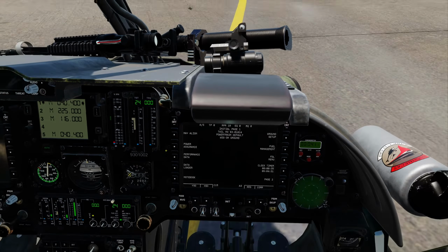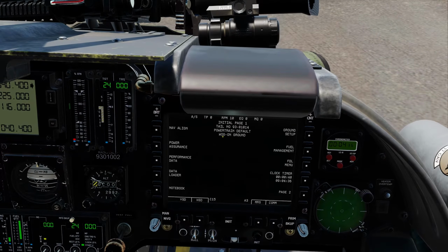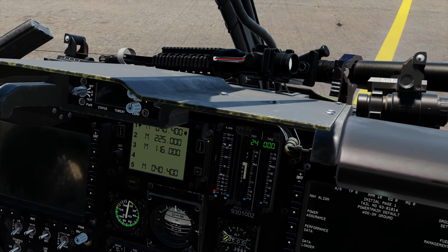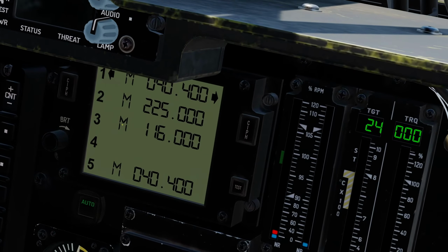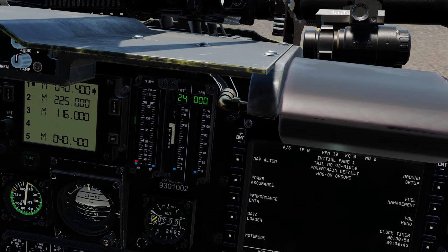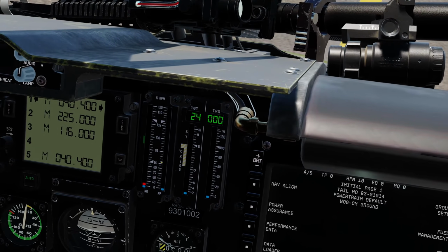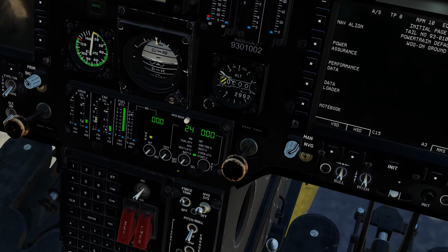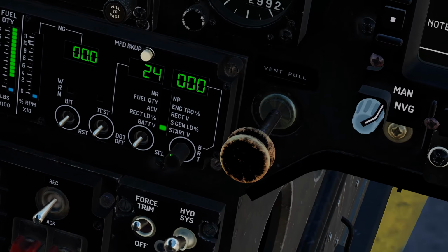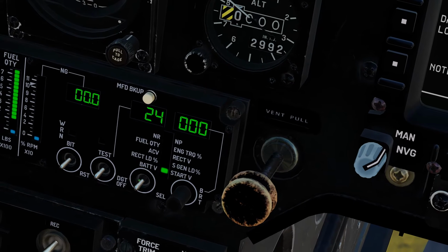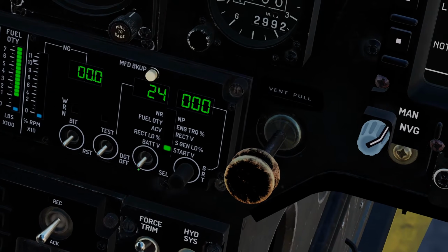And now you can see that the multifunctional display, or the MFD, has come on with the battery. Next, you can see that the RFD, the remote frequency display, which are the radios, has come on there on our left. Also, these have lit up and we've got some readings, and these are called the VSIs, or the vertical scales instruments. And importantly, this readout here, this is called the multi-parameter display, or the MPD, and we can select through this MPD to get different values, different readings, and we'll be doing that shortly.